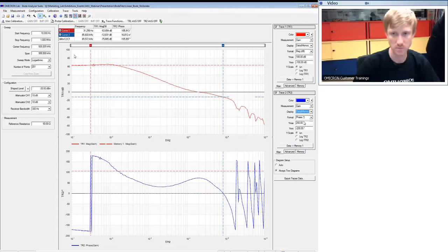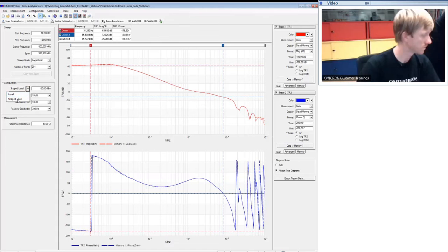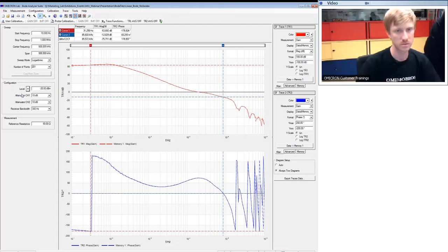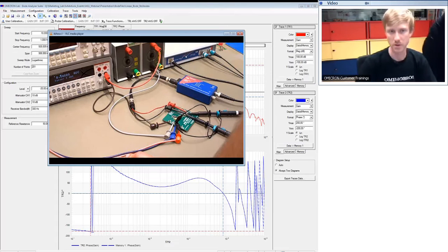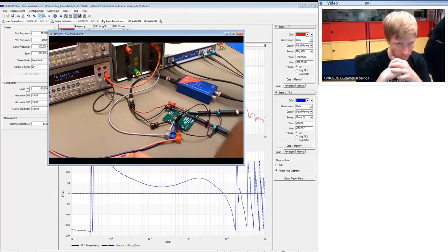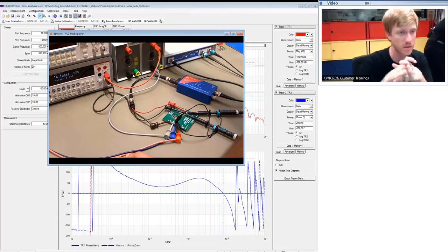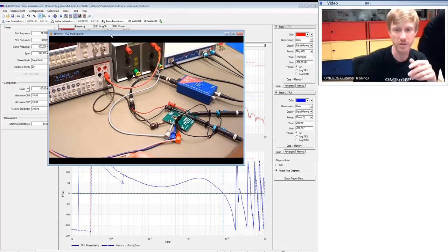Florian, do me one favor, please switch back to standard level, because we know that depending on the output current for this topology, we need to possibly adjust the level, and adjusting the level is always recommended with a level that is constant over the entire frequency range we are investigating. Okay, I will switch back to standard level, and I will now show you how Bernhard reduces the output current such that the system duty cycle changes. And the duty cycle is also part of the transfer function of the buck converter, and this means also the Bode plot will change.